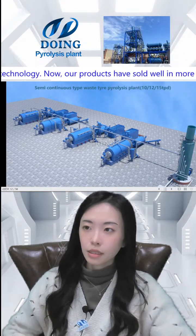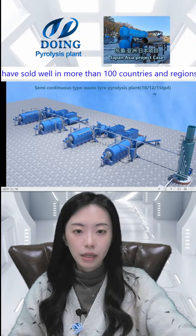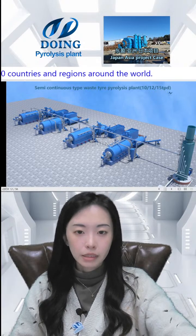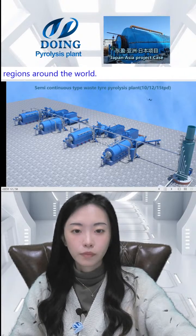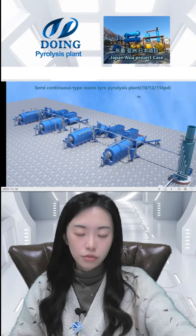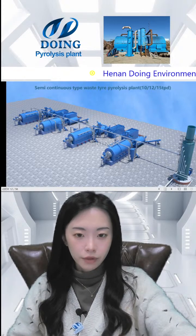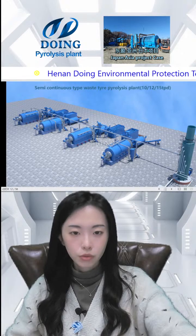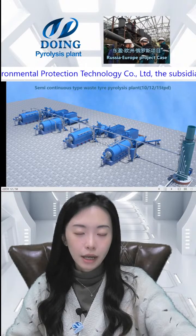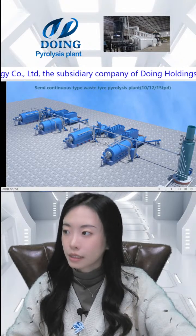And then this is the semi-continuous pyrolysis plant. Also the capacity you can see is 10 ton, 12 ton, 15 ton, the same as the batch type pyrolysis plant. But the working efficiency is not the same. It is higher than the batch type. It can work for 3 batches in 2 days. So why does it have a higher efficiency? Because we don't need to cool down the reactor to discharge the carbon black. We can discharge it at a very high temperature, more than 200 degrees, and discharge it into this.